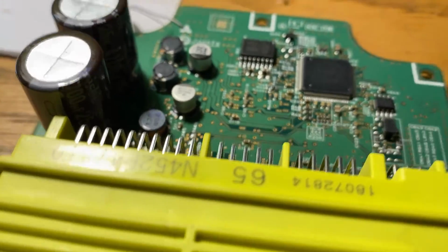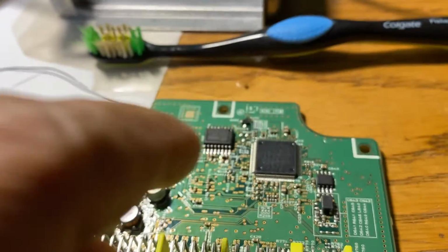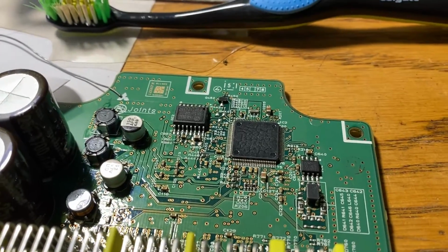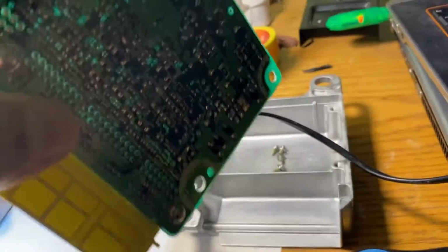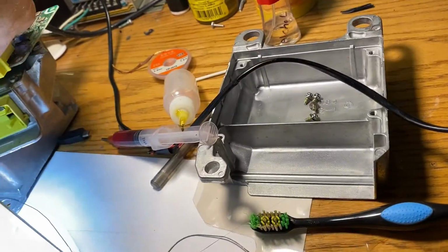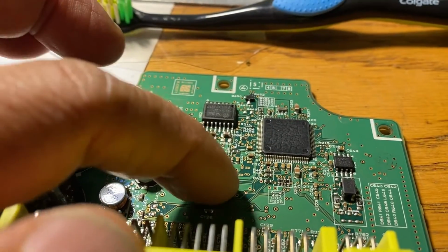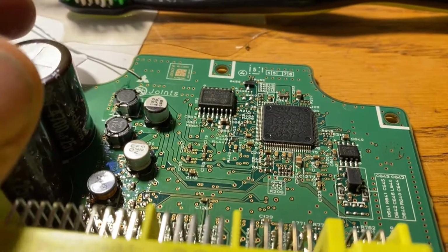So anytime you see a crystal in the airbag, don't write while in circuit. You have to take the airbag chip out, like some of the ones in Kia and Hyundai. Well, this one doesn't have a crystal. So next time when we have one with a crystal, I will show you the difference, because once you write it in circuit, you're gonna have a lot of issues.